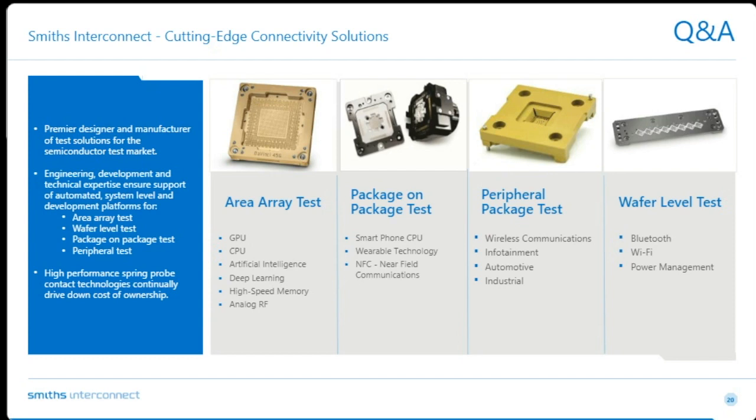I saw a pretty big one recently. We have one out in a production test environment now that is 90 by 90 millimeter. I can't remember the exact pin count, but it was a pretty big BGA device, and a large socket. We had, I think, six mounting screw positions available, and we were okay on the deflection. We didn't have any deflection issues.